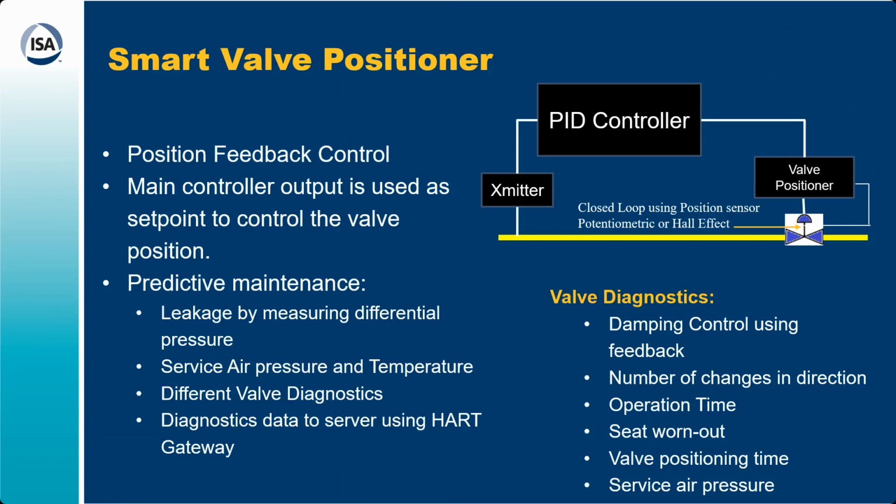When you set the valve tight, it saves its position, and when you try it again after, say, 6 months or a year, you can see that there are some changes in the valve seat, how much vena contracta is formed, and how much leakage is forming in the valve seat. Using Bernoulli's theorem, you can estimate the leakage in the valve, because this is a continuous leakage.